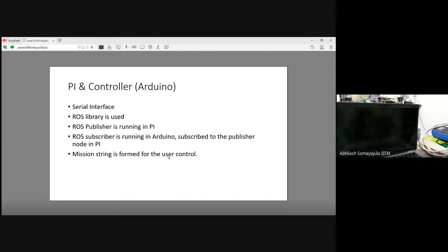It is better to publish the RPM directly and ask the Arduino to match that RPM. You calibrate only the RPM of the motor and let the hydrodynamics be a separate portion of it. No, okay. So no, here anyway, it was all open loop. I mean, I was telling that it will be like generally how we do here. It's better not to do it, is what I'm saying. It's better to encode, rather than the speed of the vehicle, the RPM which you want to achieve.